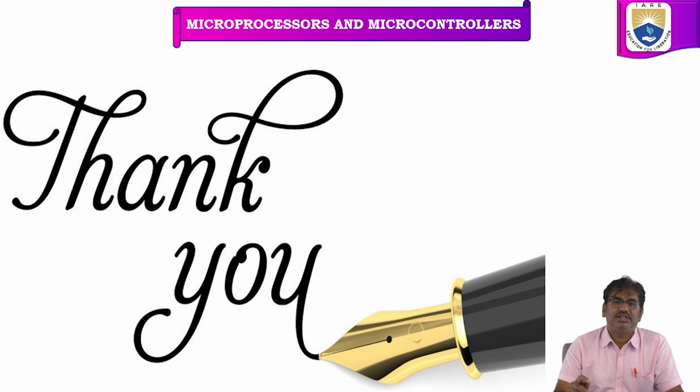Thank you. In this session, we have discussed a few instructions related to arithmetic operations, mainly related to multiplication, which are MUL, IMUL, and ASCII adjust after multiplication. Next, we discussed the instructions corresponding to division operations, which are unsigned division DIV, signed division IDIV, and ASCII adjust before division, which is AAD. Next, the data conversion instructions: CBW, convert byte to word, and CWD, convert word to double word.